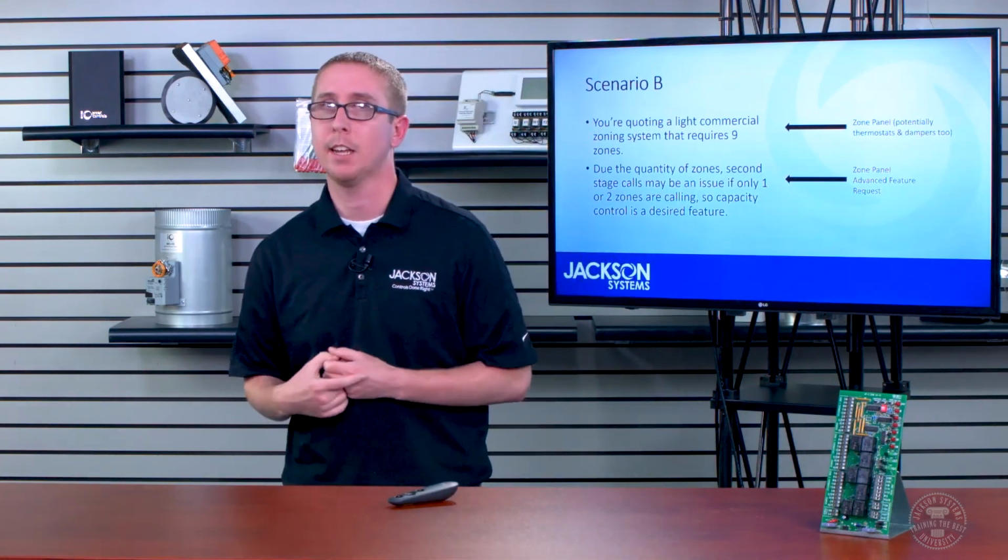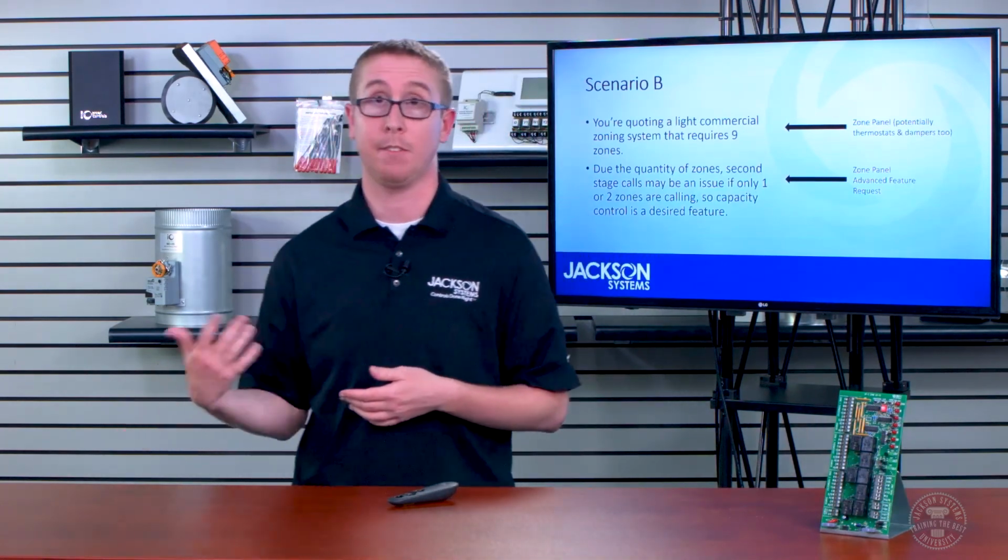Those are power stealing stats. What about a battery-powered Wi-Fi thermostat, like the Sensi and Braeburn both have? I think that would work. I believe that one is only compatible with conventional equipment. But power stealing is definitely a no-no. If it's not using a common wire because it's power stealing, you could not use it. If it is battery powered and just doesn't have a common, you could. That said, very few Wi-Fi stats are battery powered, because Wi-Fi requires high power consumption and you would be changing batteries a lot.